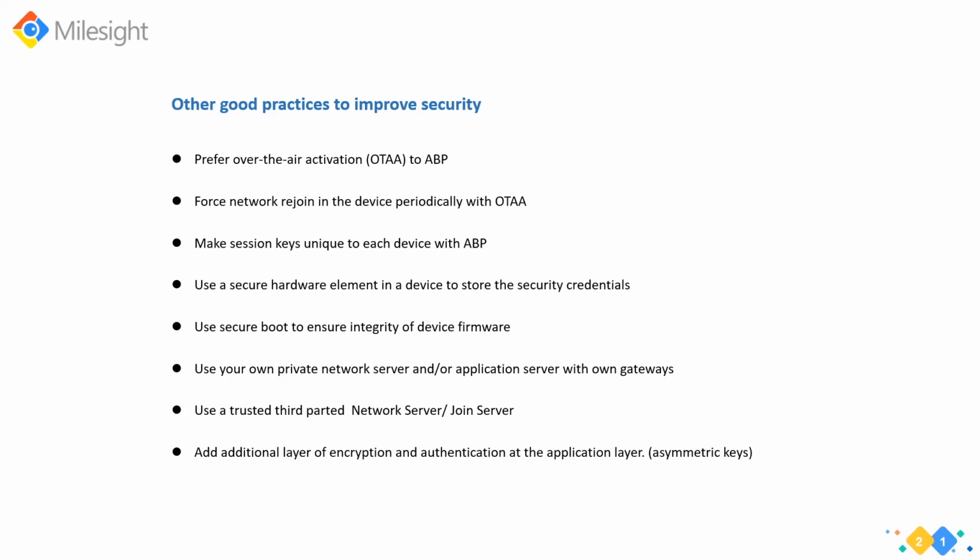So here are some other very good practices. Use the OTAA provisioning, where the keys are dynamically negotiated between an end device and the network and application server for each session. And force the device to rejoin the network periodically to change the session keys. Maybe after several months, the network can ask the end device to rejoin, to send a join request again, in order to change the application session key and network session key.